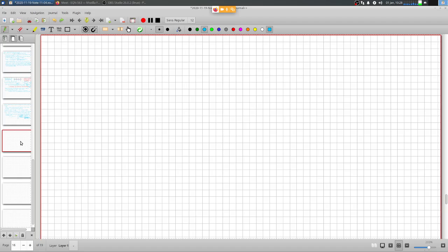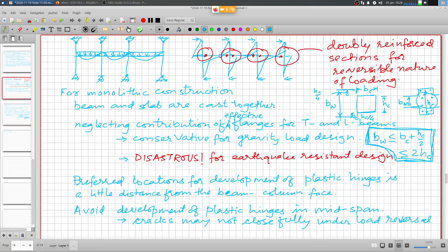So what is the shear force that we need to design for? As you can see, for the earthquake load, the bending moment is a straight line from negative moment here to negative moment here, so it leads to a constant shear force.